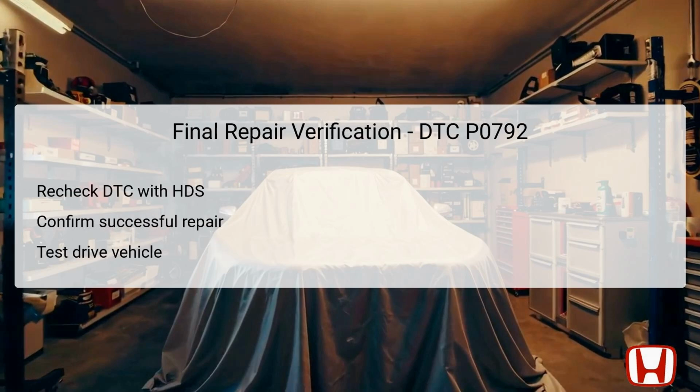To verify the repairs made in response to DTC P0792, it is essential to conduct a final check with the Honda Diagnostic System, HDS. Begin by rescanning the vehicle for any DTCs to ensure P0792 does not reappear. A successful repair will reflect the absence of this trouble code and should confirm that the newly installed or repaired components are functioning as designed.